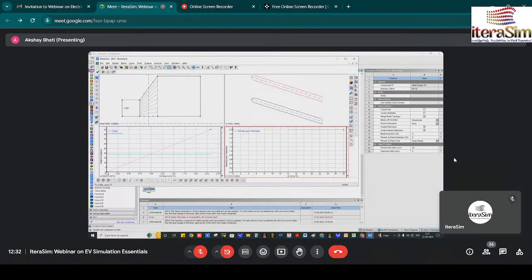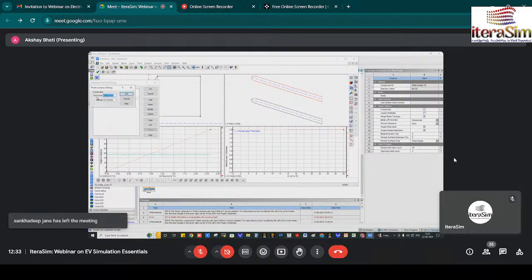And also the angle, according to what you want. If the blade angle at my leading edge is 20 and at the outer edge is 25, you can do that. So you can adjust accordingly. Another one is the inlet domain, that is the outlet, and that is the fan body. So if that is horizontal, let's say we want to generate a small fan, so let's say we put it at minus 15. We don't want a bigger inlet.